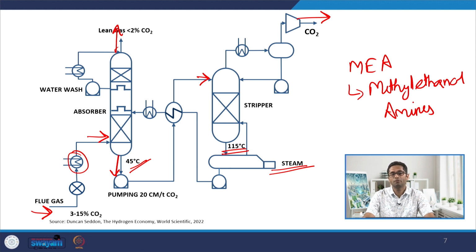so you need to be careful while saying that if I am capturing CO2, it doesn't come at an expense. It does come at an expense, in the form of using much more fuel, and it's going to be expensive as well. And after the CO2 is released, the absorbing liquid can be recirculated back to the absorber, where it's cooled back and enters into the absorber. Then this is how the whole process looks.